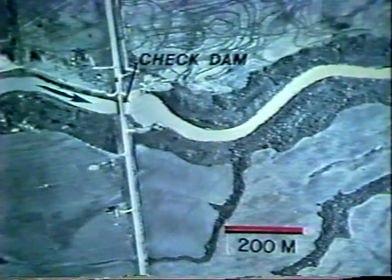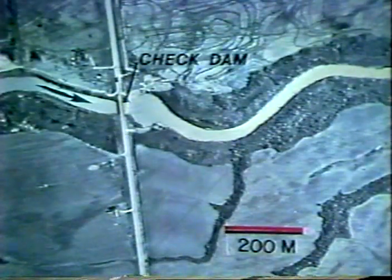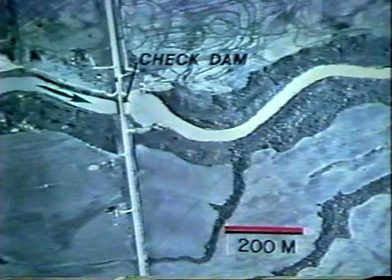They have performed satisfactorily on many small streams, but scour of bed and banks downstream from the dam is a common problem. Here, a check dam of concrete grouted riprap is being undercut by scour. At this site, a channelized stream has been widened and deepened downstream from a check dam.